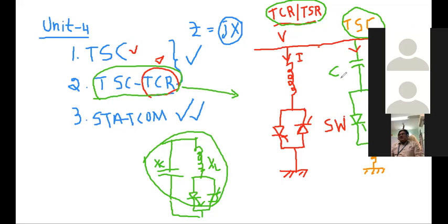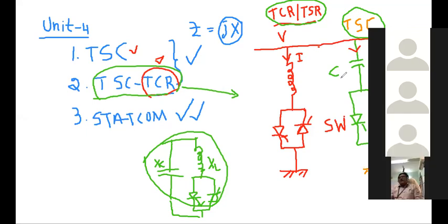The excitation is very important. Generally the excitation will be changed by changing the field rheostat, that is, depending on the field current. Once you increase the field current, then excitation, that is E, will increase. Once you reduce the field current, that is excitation, then E will reduce. Then, with respect to the terminal voltage, current lagging or leading takes place depending on the E and V magnitudes. Then real power, in the synchronization experiment, we'll go back to the fundamentals and discuss some of that, and we come back to this again.